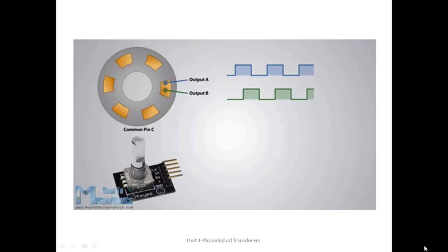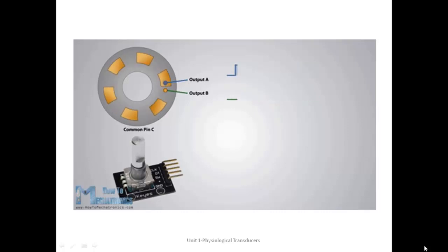And the third one is the sliding contact encoder, where we have a completely insulating disk, and we have certain conducting slots in between. Two pins, when they come in contact with the conducting area, initiate an electric pulse, and that pulse can be recorded. In 1 minute, how many pulses were generated, we can record how much rotatory movement must have taken place in 1 minute. Okay, so these are the common devices called encoders.